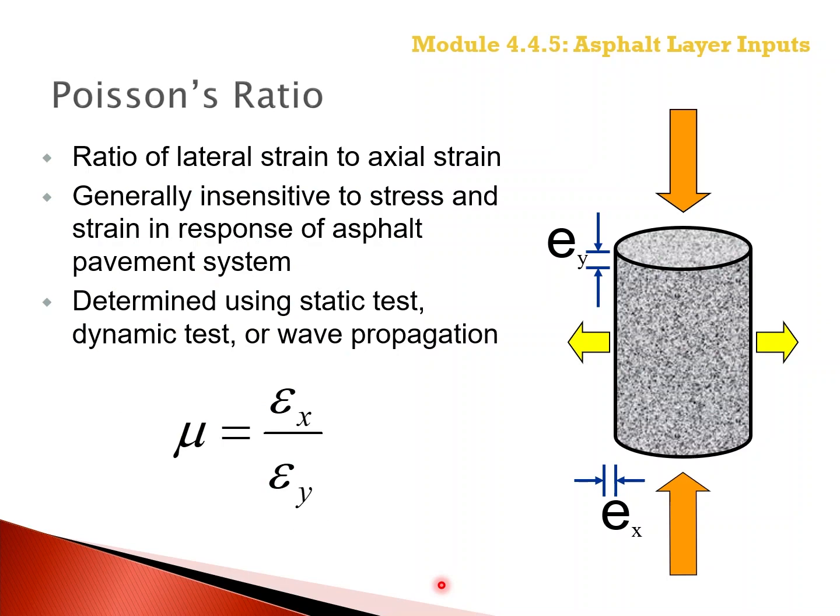Poisson's ratio is the same as defined for the other pavement materials discussed in the earlier modules of this course. Poisson's ratio is used with a dynamic modulus to calculate the critical responses in the asphalt layer over time. As such, it should represent short-term aged specimens.